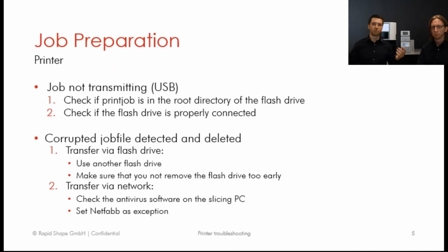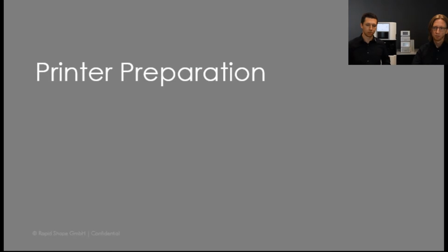Of course, we haven't got a corrupted job file in here yet, so we cannot show you. That's a little bit sad, but you may have seen this message, and it's an easy workaround. Check the antivirus software, set NetFab as an exception, and everything should be fine again. Okay, so I think no questions for now, so let's continue with the next one.